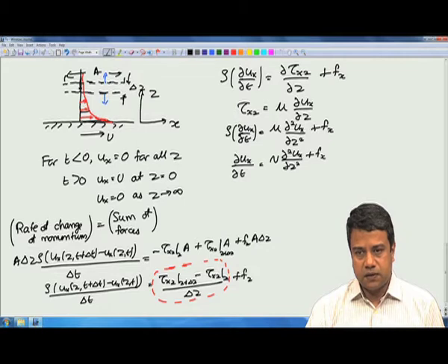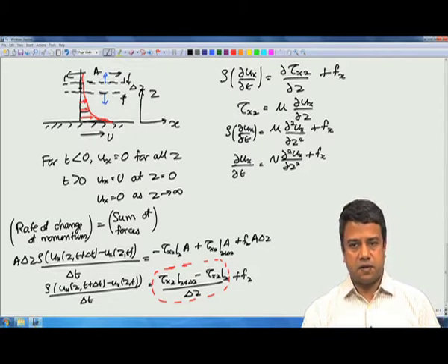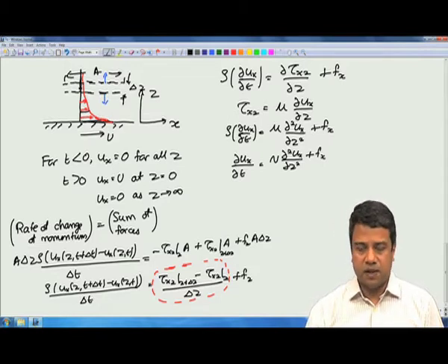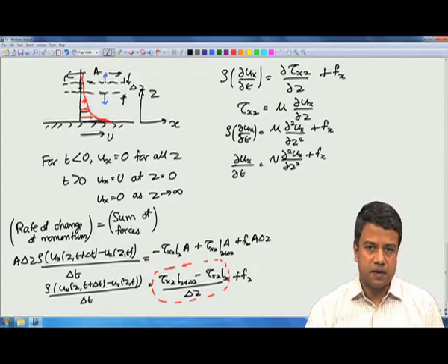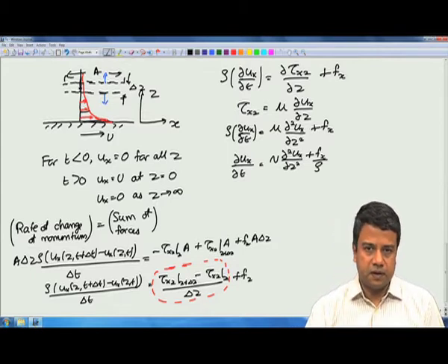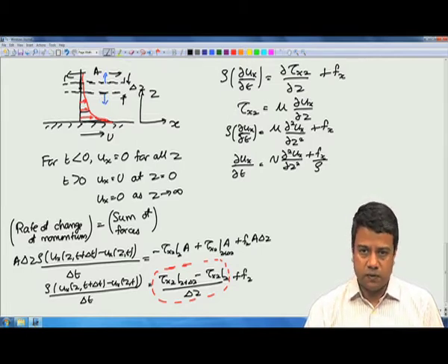Once again, you can see that you can get this equation from the concentration or temperature equations just by substituting the x velocity instead of temperature or concentration, the momentum diffusivity or the kinematic viscosity instead of the mass or the thermal diffusivity, and the force; I should have a density there as well, so if you divide through. These equations, all three for mass, momentum and energy in this simple configuration, have exactly the same form. And therefore, we can solve them using exactly the same framework, for either mass, momentum or energy.